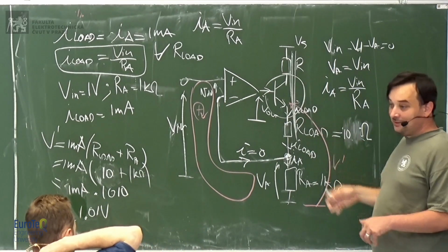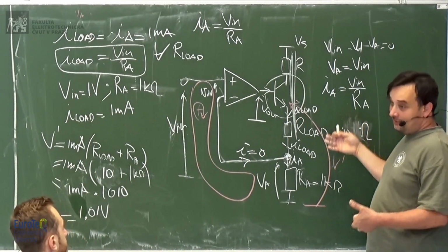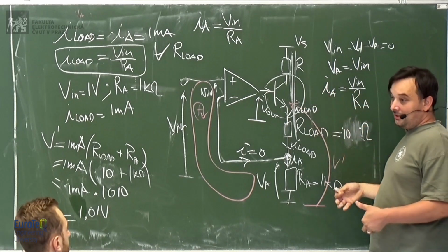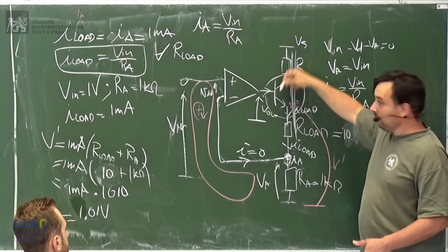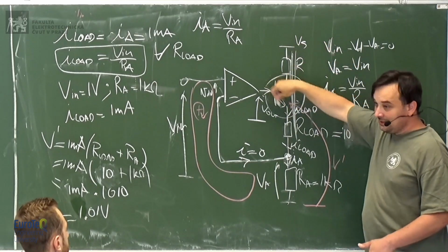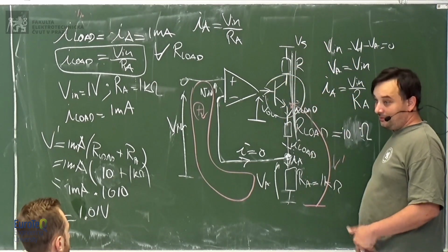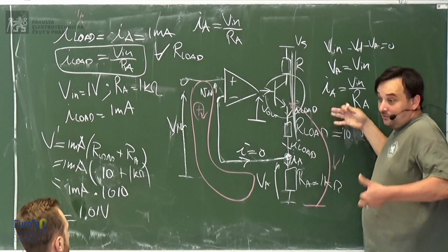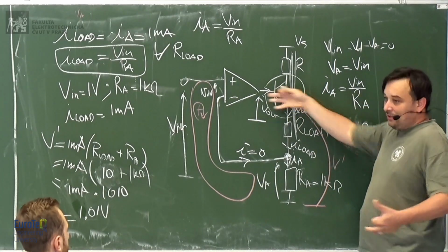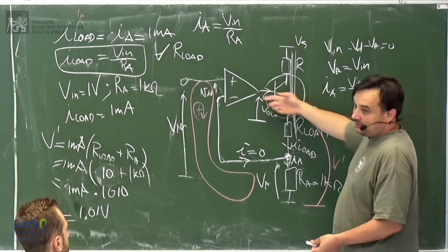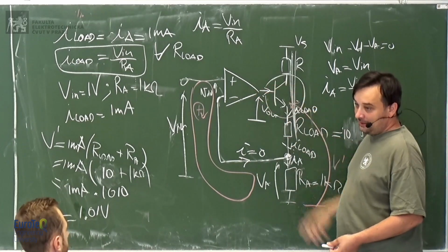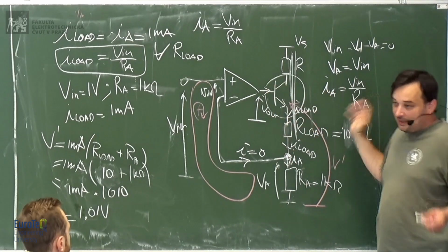This is just to show that if you want to create a current source with larger current supply, you need a transistor so the current comes from here and not from the operational amplifier, if the current that you require is too large and cannot be provided by it. But for small current, if it can be provided by the operational amplifier, fair enough, you can avoid the transistor.